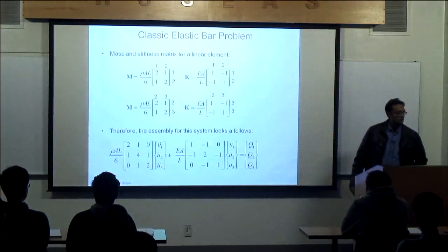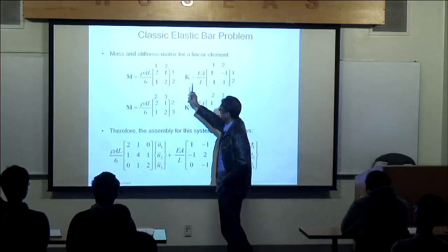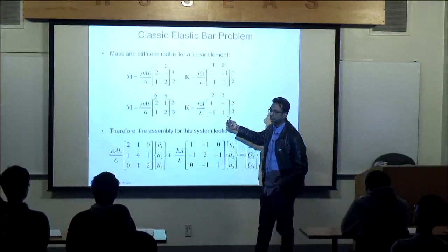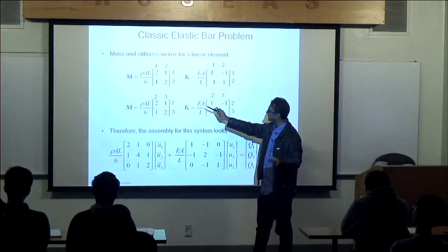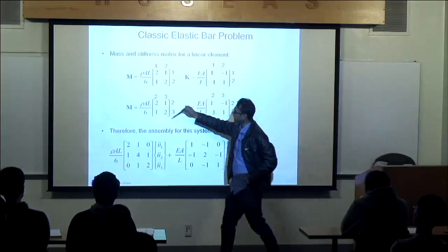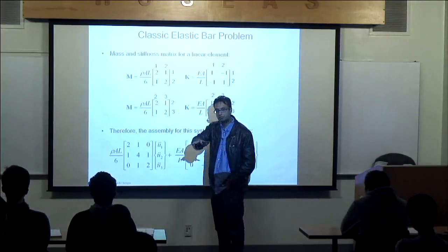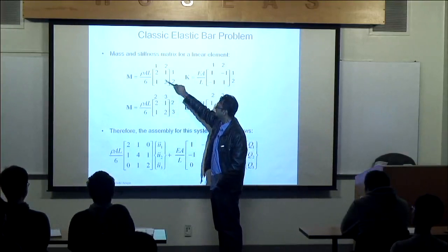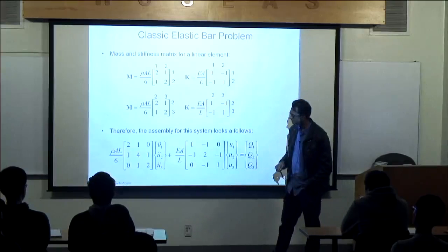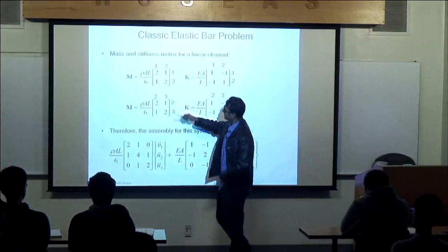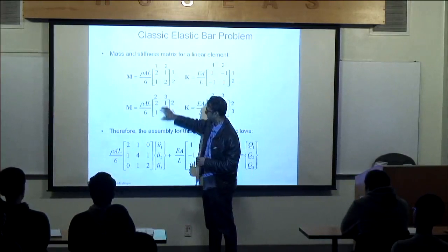And I went in and got the mass and stiffness matrix for element 1 and for element 2. I did the assembly. Everybody knows how to do assembly here. The only new part could be this one here, but I already told you, if you check it at home, you'll see that these are the mass matrices you get. So no problem there. I can assemble it, and basically all you get is a superposition of this over this. So you get 4 in the middle.